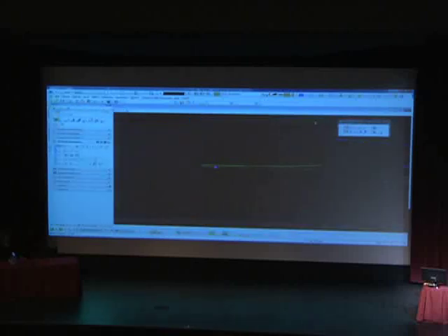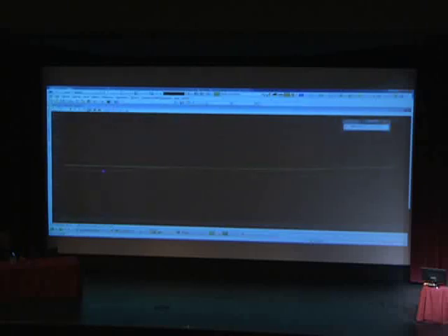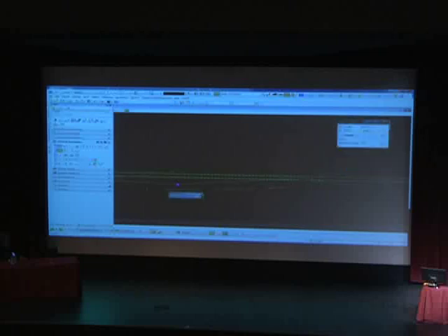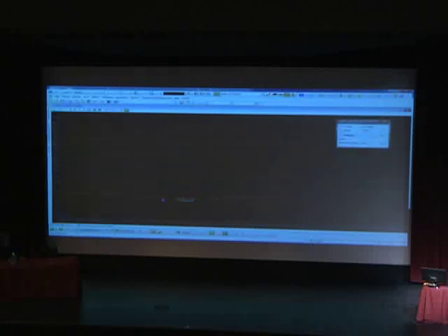That purple dot that you see there was the actual flow line of a culvert that was there, so I want to know where that is. That green line up top that's pretty smooth is our edge of pavement that was referenced in. I did a profile by slope saying it was a 0% slope. Then I offset that 2 feet to say that's my upper bound. I don't want my ditch line to go more than 2 feet within my edge of pavement.